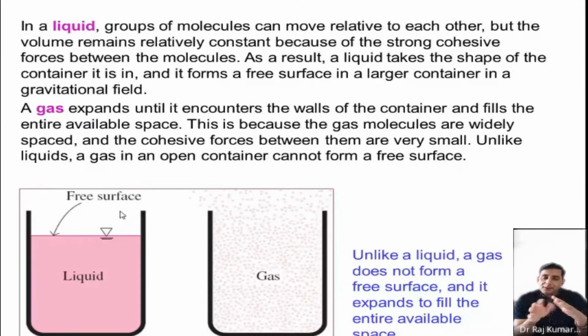So individual particles may have some motions, but as a whole, the fluid is completely at rest. Whatever individual particle motion and stress there is, as a whole it comes to zero. So individual particles can have it, but for the entire fluid to be at rest, it should not have any shear.